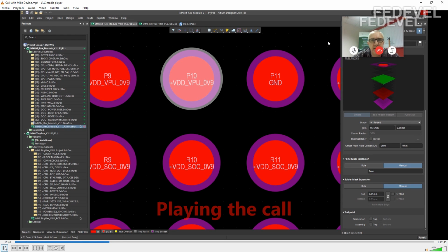Okay. And if you've got a large number of holes, the prepreg, like I say, typically is a thin prepreg. It was not sufficient to fill all the holes 100%. And that's where you would then end up with some air entrapment in the center of the hole.